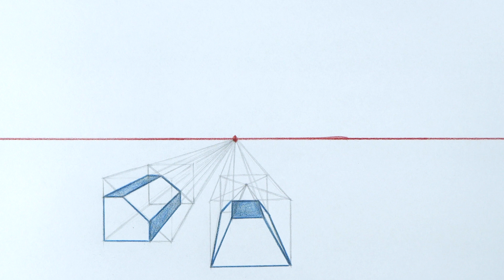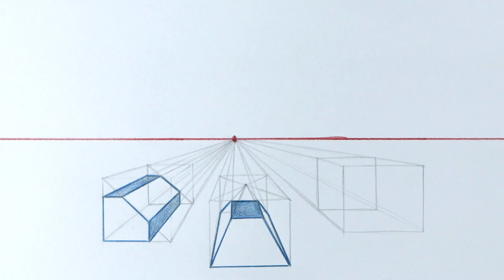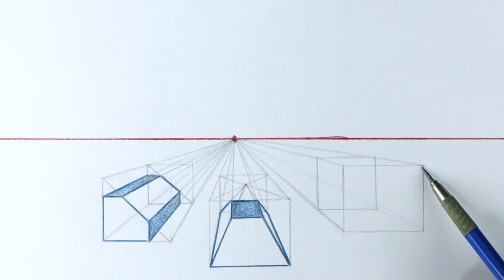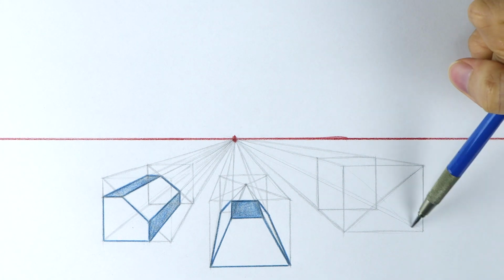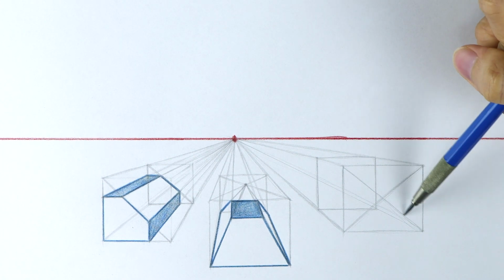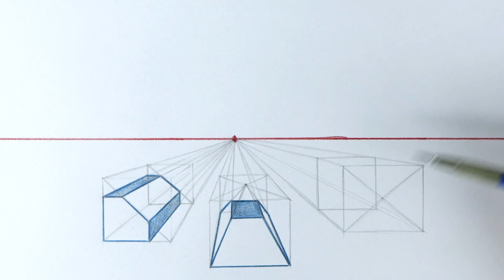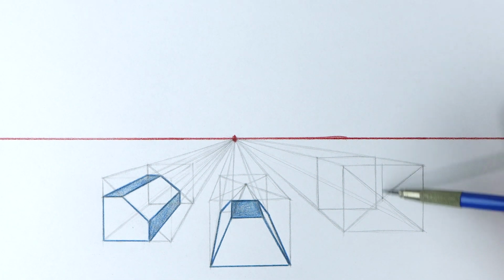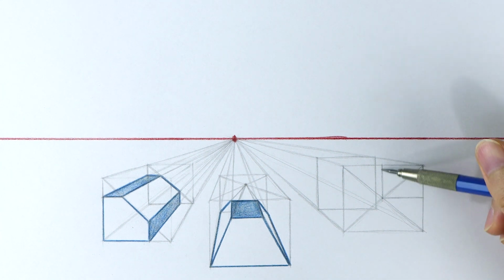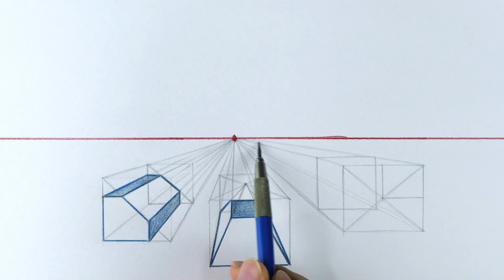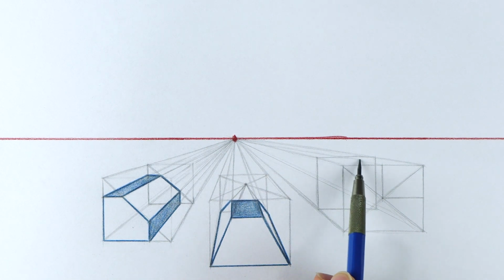Here's another example. Let's put this box to the right of the vanishing point. Suppose we want to cut a chunk from the top right corner, and we want this chunk to be exactly 1/4 of the shape. So we can use the X method to find the center. Then we'll draw the cut line to remove exactly 1/4 of the front plane. Connect the two corners that were just created to the vanishing point.